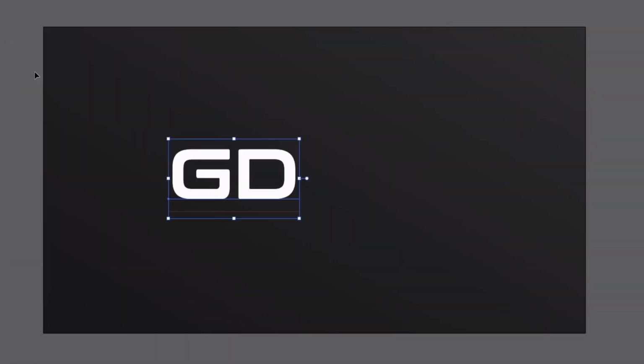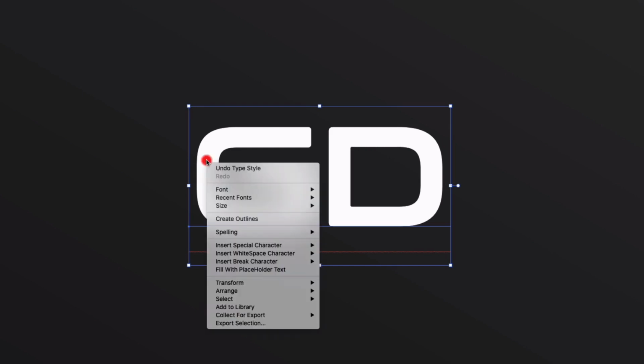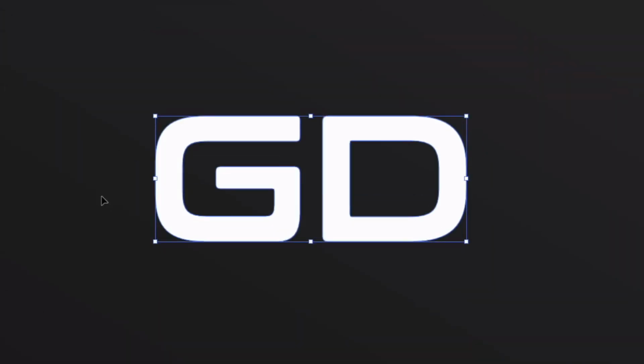So you can see this is a nice clean sans serif font, and it's going to work really well for something like a monogram. When I chose this font I was really looking for something with very straight edges and very consistent line weight, which is what this typeface uses. Now to make a monogram from this I need to customize it, so what I need to do first is create outlines. So I'm just right clicking and selecting create outlines, and what I'm doing in both of these options is stacking them on top of one another.